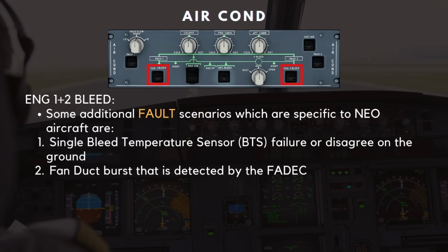Additional failure scenarios specific to NEO aircraft include a single bleed temperature sensor failure or disagreement on the ground, and a fan duct burst detected by the FADEC.